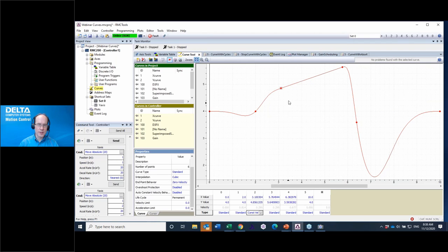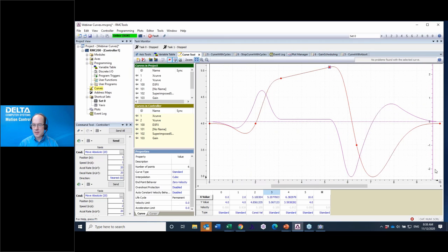As I'm making a curve, it's important for me to know what kind of velocities I'm generating. I can make a really cool curve, but if it's going to go 100 inches per second and my system can only go 30, that's a problem. So I can click up here to show velocity. That shows the velocity with the scale on the right-hand side. We see it goes from about 2 down to -6, so a little bit fast right there. So adjust that. Okay, now we're from about 1.5 to -2. Nice and slow. I can do the same for acceleration. I see the accelerations here, scale on the right, light blue. So I'm going from 4 to -4. That's plenty easy. Turn those off, and then I can see my curve here.